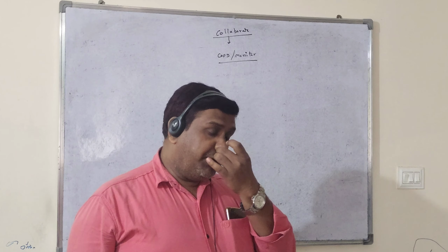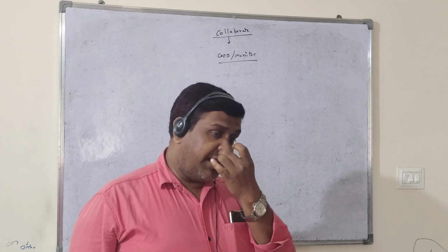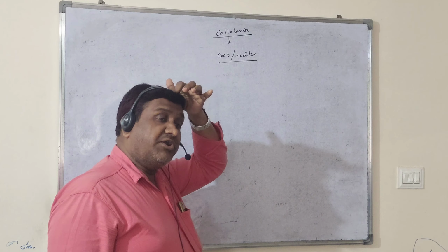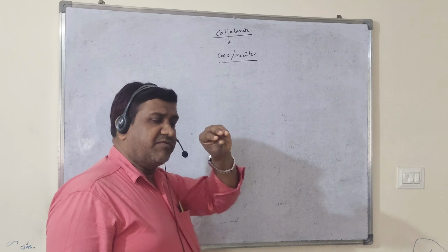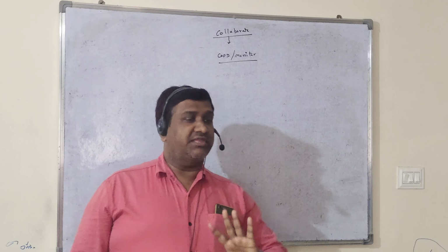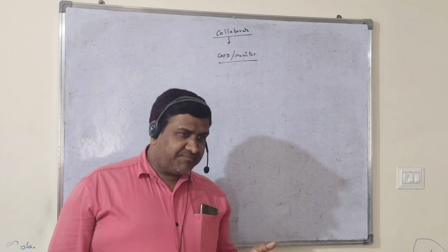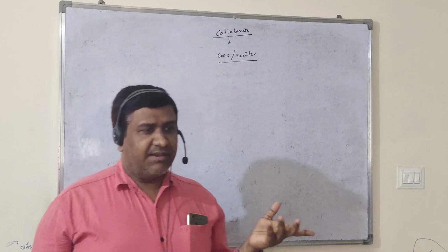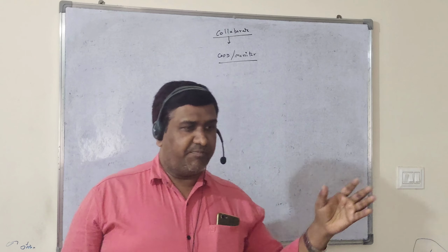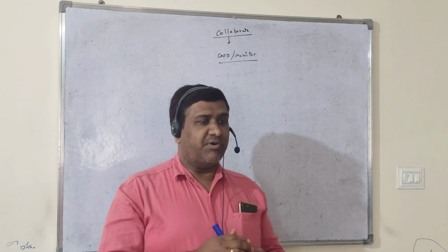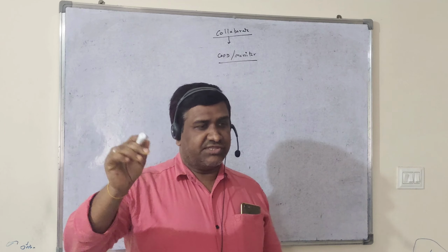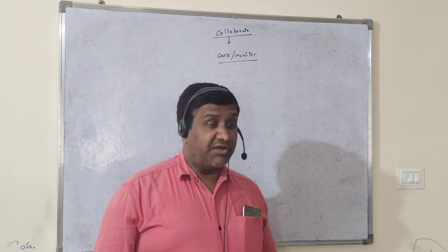So how will we take those components from one file to another file? That is the process we will follow with Copy Monitor. Very few components only we can copy paste from one file to another file. Within the same file in AutoCAD, with the help of copy we can use that component, copying and pasting in multiple places. There is a CO command, CO for copy, and wherever you require, you just copy paste. So it is possible in AutoCAD.